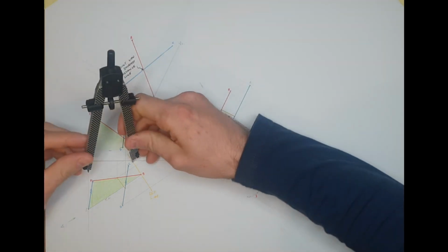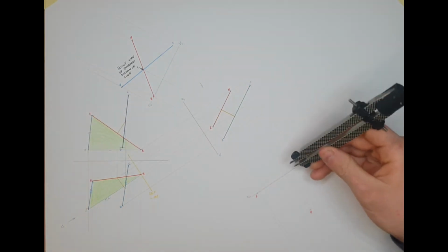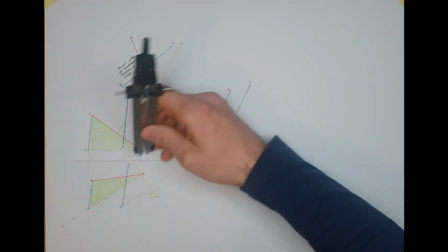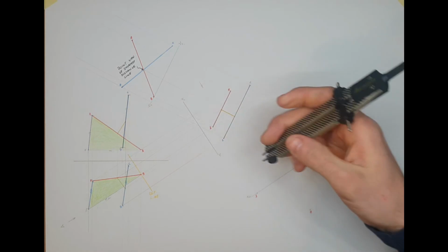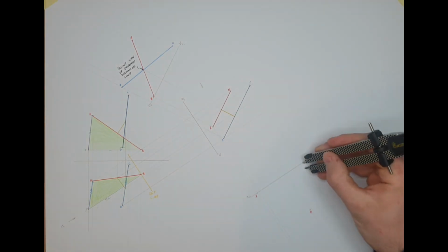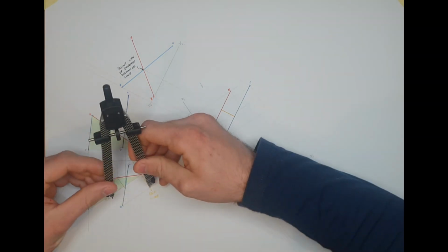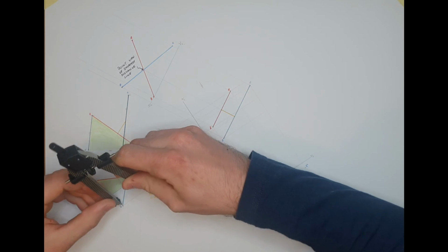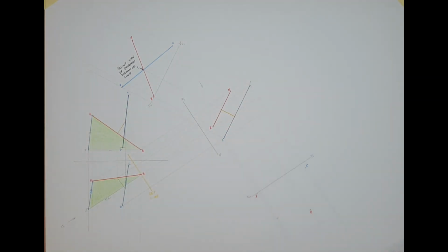I want to go back and find my point C distance. And don't forget, all I'm doing here is I'm skipping a view and working back from the XY line ideally, but we don't have space. So back to C and down to point C. Last point. Down from the reference to plan, down to D. And out here to D.